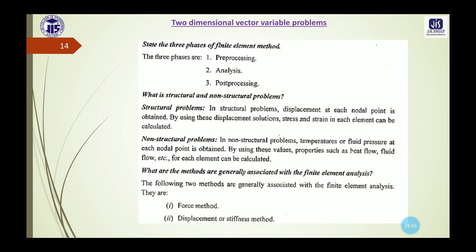And in case of the non-structural problems, the temperatures or fluid pressure at each nodal point is obtained, and by using these values, different properties such as heat flow, fluid flow, etc. for each element can be calculated. So these are the classification of the finite element modeling problems, like structural and non-structural problem.